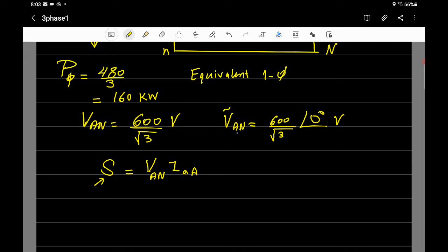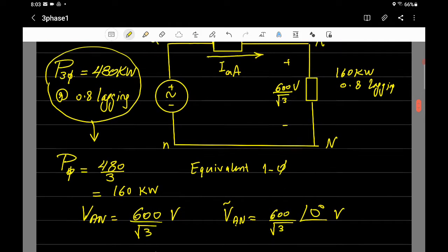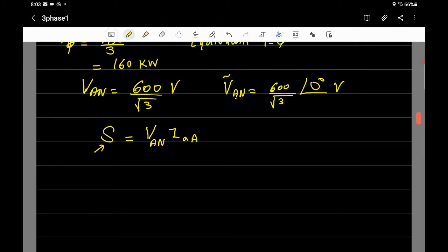I know the voltage, yes. Do you know S? No. Do you have information to help you find S? Yes. What information? I have power and power factor. Well, how does this help? Do you remember, there's something called the power triangle. Okay, let's just try to make it nice. Power triangle. All right. Oh, this is the triangle. Here is the power P, Q, S, and angle theta.